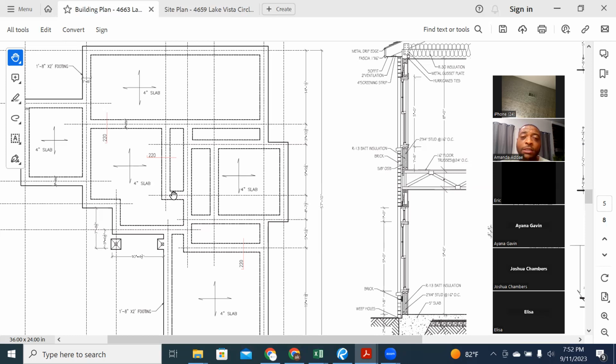It's similar to a roof. Maybe I want to do architectural shingles. Maybe I want to do a metal roof. Maybe I want to do some kind of fancy roof. The city is not going to care so much about that, but they want to make sure that you put the proper underlayment there, and the proper flashing to prevent leaks. So they look for those things. So long as you've passed those things, you can go ahead and lay the shingles over your roof.